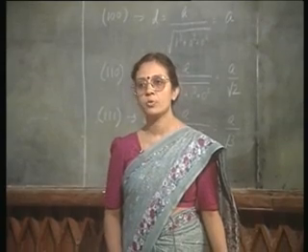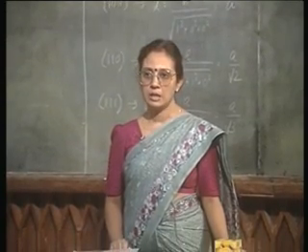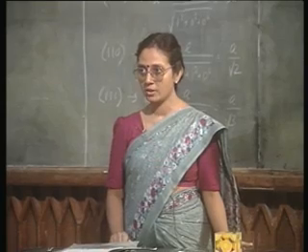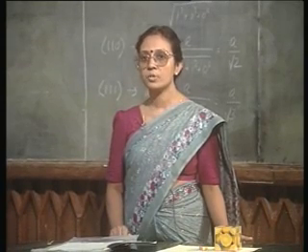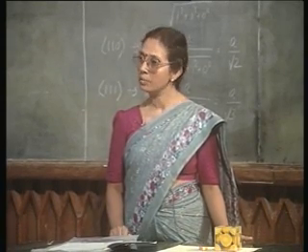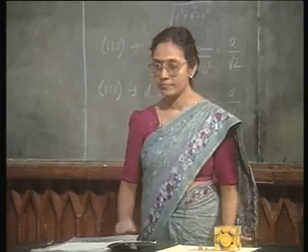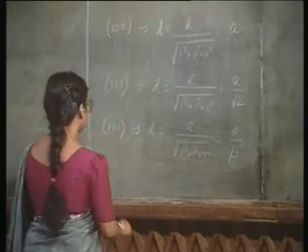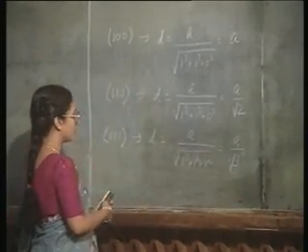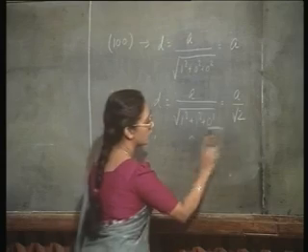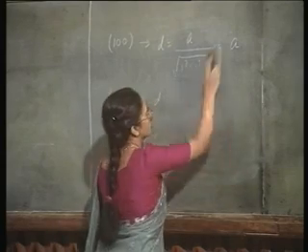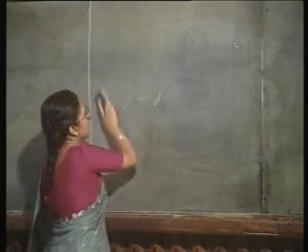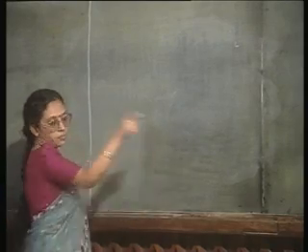You have exposed it to a selective etchant which is going to expose the 111 planes. Now, the angle between the 100 plane on the surface and the 111 plane which you are going to expose is going to be given by this relationship.